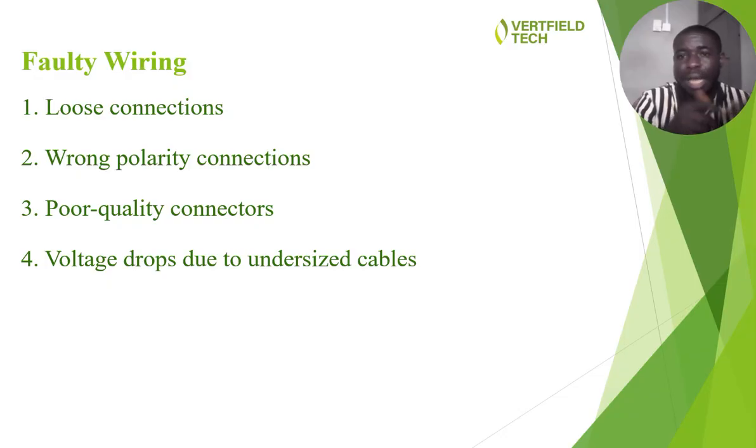At times, most technicians, because they do not have an idea of the right tools or components to use for installation, cut off the connectors on the panels, which is a wrong practice to use on the field.